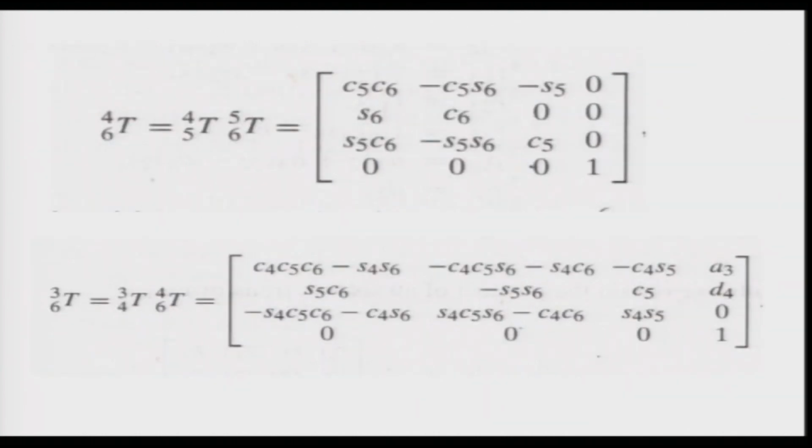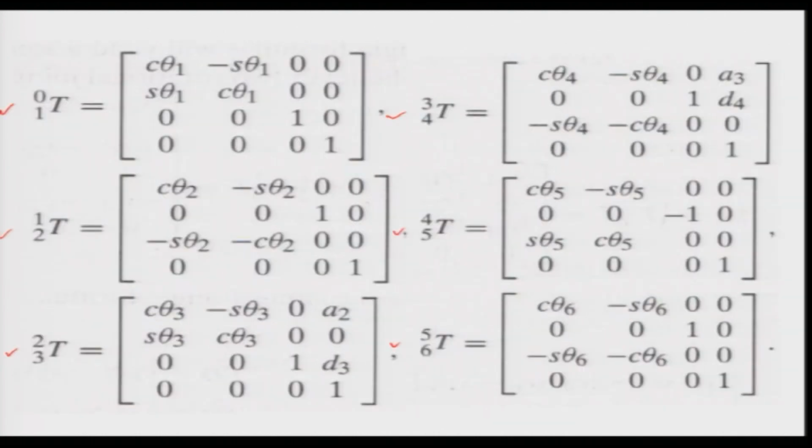Now, what we need to do is multiply all of them together, okay. But something to note here is that if we multiply all of them together and get our final matrix T0 to T6, and then try to solve the inverse kinematics, it is not possible to solve, okay. Why? Because, as you will see in the next few slides, there are so many sine and cos terms.